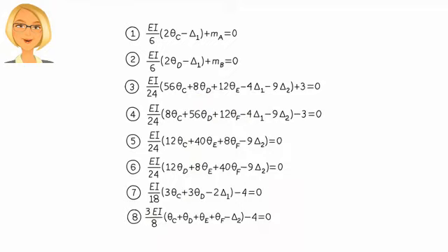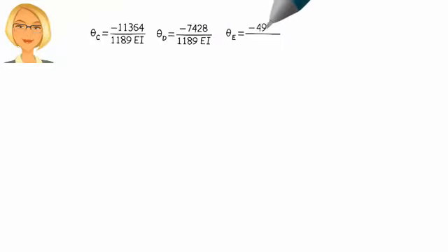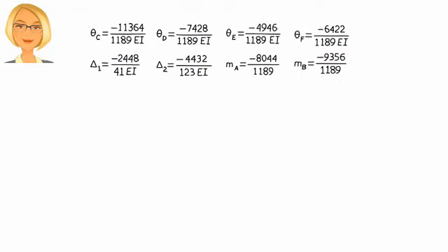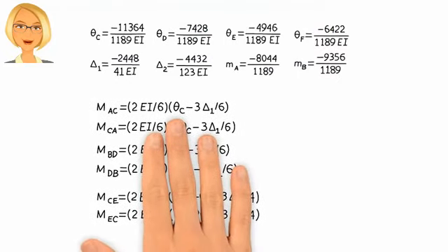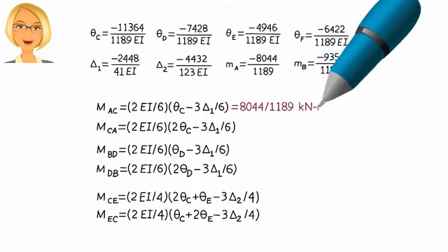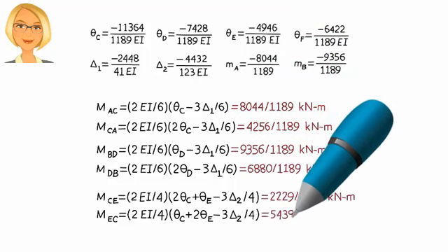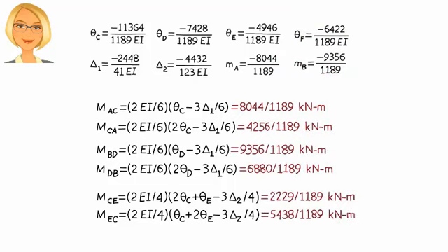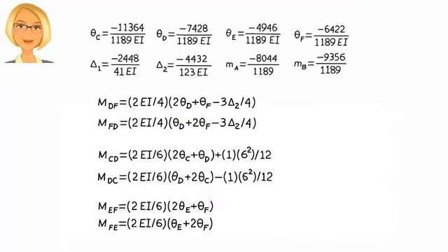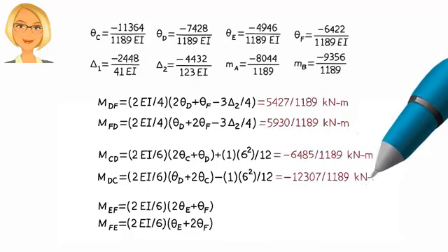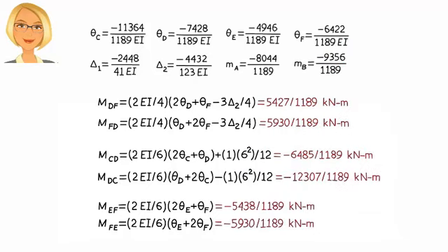Solving all 8 equilibrium equations simultaneously, we get when we substitute these slopes and deflections in the slope-deflection equations, we get the following values for member end moments. Now we can calculate member end shear forces like this.